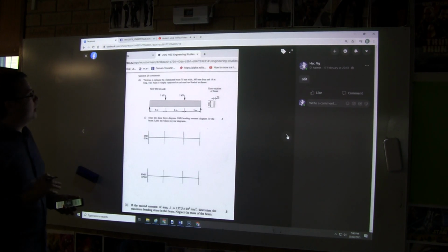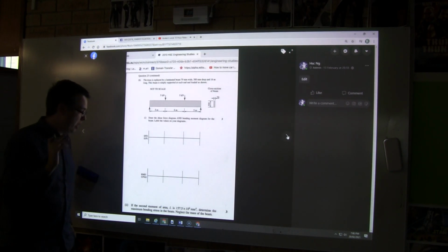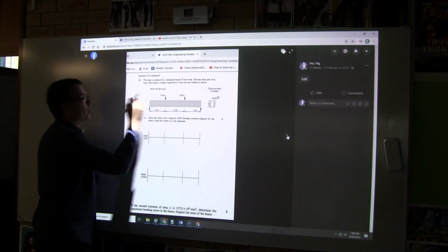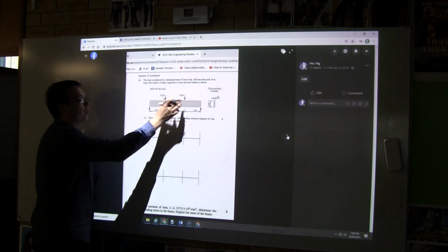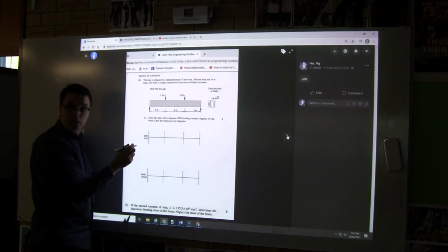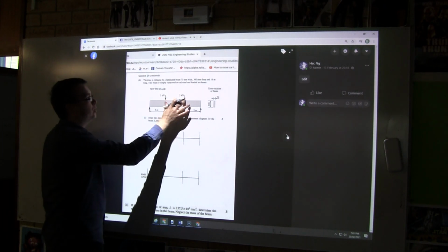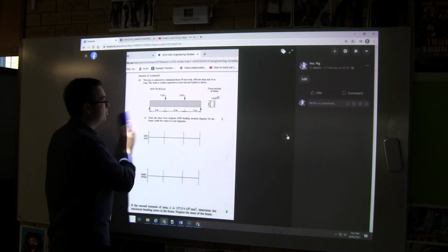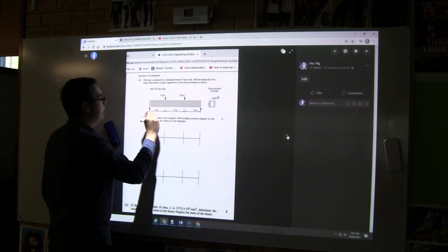Okay. This one, I think the answer in the book may be wrong, which I'm hesitant to put a video out there and make a big claim. But what we can say is, in this situation, we've got a symmetrical beam. So what's our loading going to be? What are our reactions going to be? 5 and 5. If our total load is 10 and it's symmetrical, we're going to have 10 divided by 2, which is going to be 5 and 5.